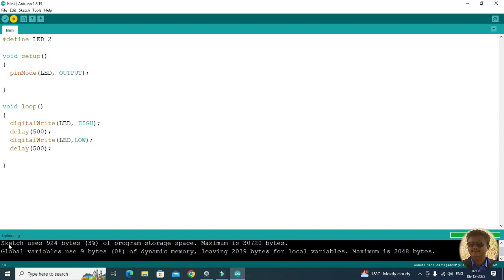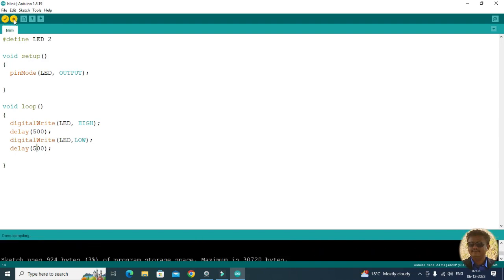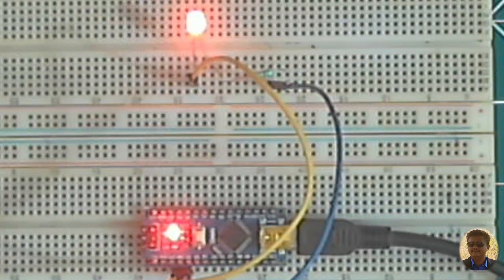It's uploading. Okay, right, now the LED is blinking faster. Now you can just change the delay time and you will find that the LED will blink faster or slower. So that's for today. In the next class we'll explain more concepts in Arduino programming.